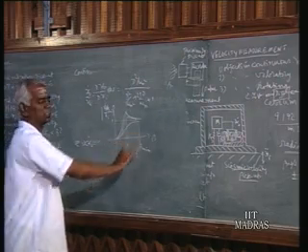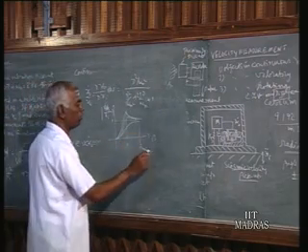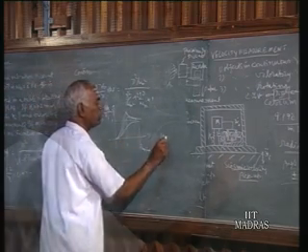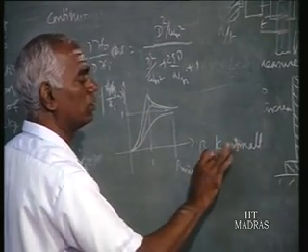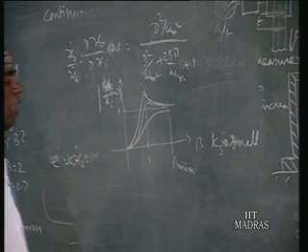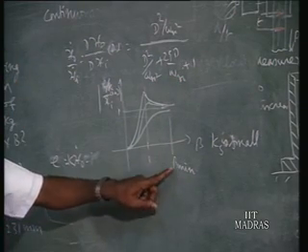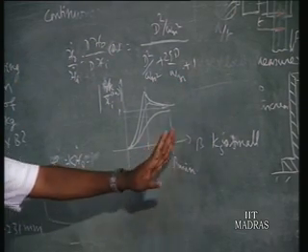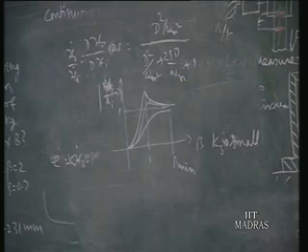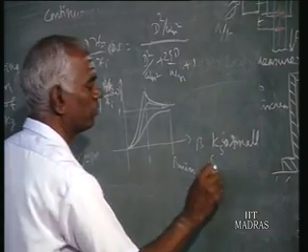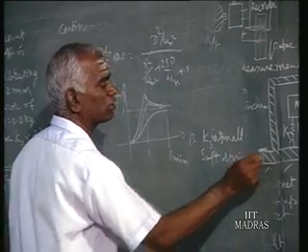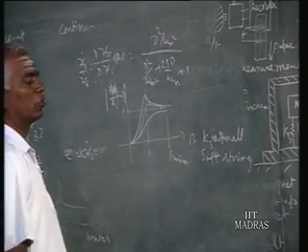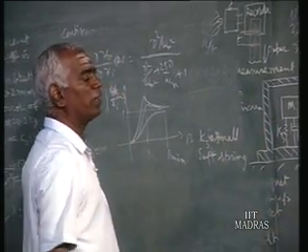So the same considerations apply. Here also Ks should be small. For having a smaller beta minimum, the frequency range should start from lower velocities. So Ks is small, that is a soft spring. We go for the soft spring. Instead of having a larger mass, we can have a softer spring, so that there is no loading effect on the vibrating body.